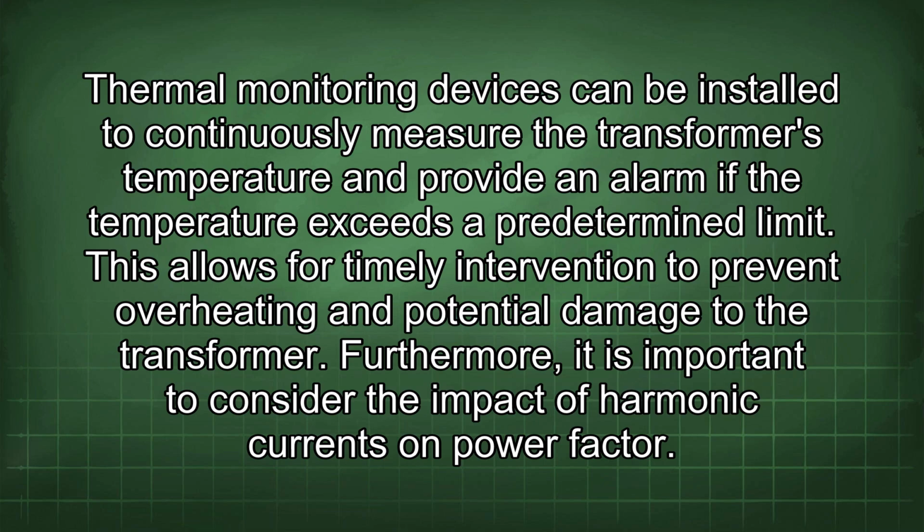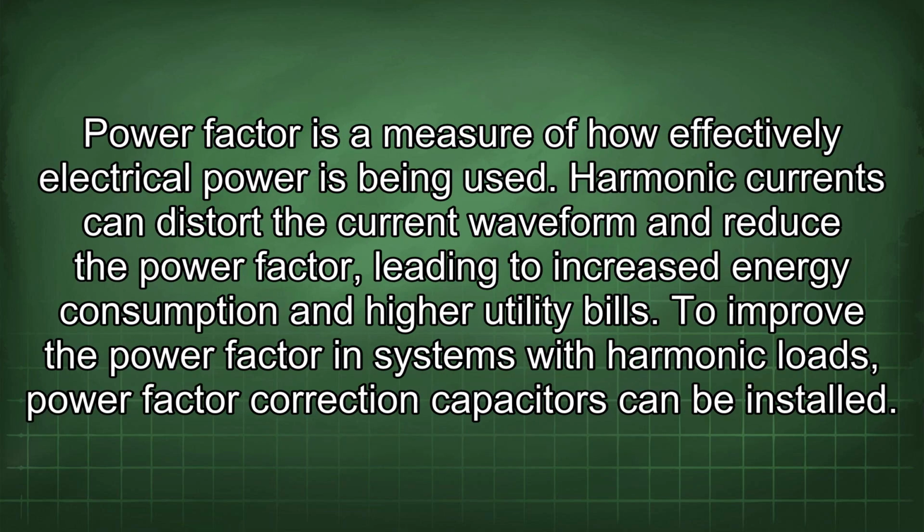Furthermore, it is important to consider the impact of harmonic currents on power factor. Power factor is a measure of how effectively electrical power is being used. Harmonic currents can distort the current waveform and reduce the power factor, leading to increased energy consumption and higher utility bills. To improve the power factor in systems with harmonic loads, power factor correction capacitors can be installed.